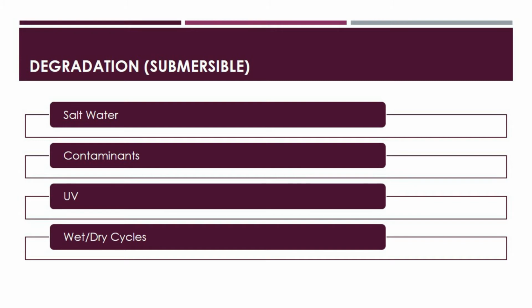Self-healing processes, on the other hand, are actually possible for switchgear. So for example, SF6 can disintegrate and totally recover, as SF6 gas can do that when exposed to an electric discharge. Solid insulation failure can result in lasting harm, though, by reducing the solid insulation's insulating qualities. And at normal operating voltage, this will eventually break.